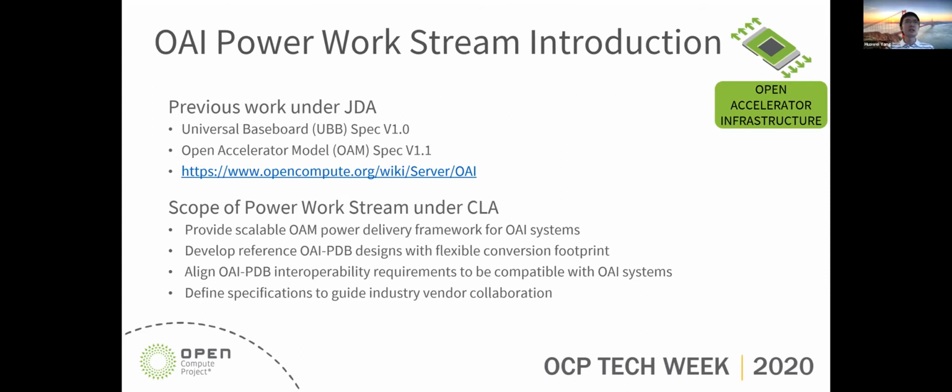A second one is we would like to have reference PDB designs with flexible conversion footprint. Basically, we have multiple and different VR solutions from different VR vendors, and they all have different form factors, different footprints, and different power specs, and it becomes more challenging to combine them.